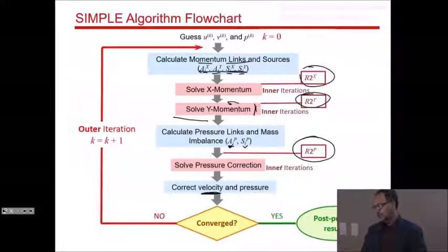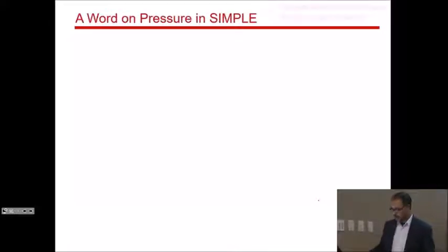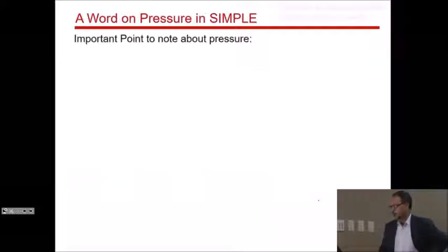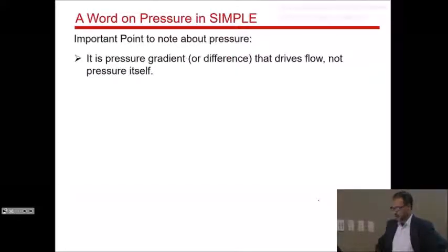So that's the overall simple algorithm. So let's talk a little bit about pressure. A couple of important points to note. First of all, the pressure gradient or difference is what drives flow, not the pressure itself. So you have to be careful, or not careful, but you can use that to your advantage.